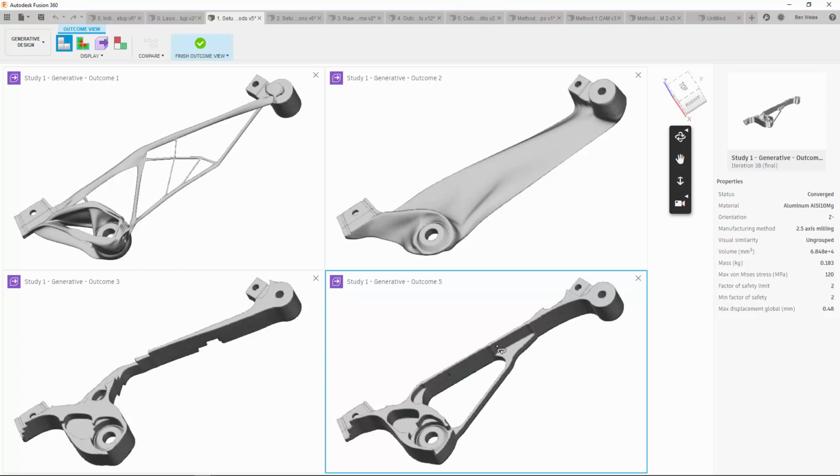On the right, we did like this triangular shape, but again, we'd like to get rid of that tall, thin wall. These designs are also a little bit on the spindly side for what we would wish for in a design for a part like this. It's not going to work well for off-axis loads we haven't modeled and general wear and tear and fatigue.